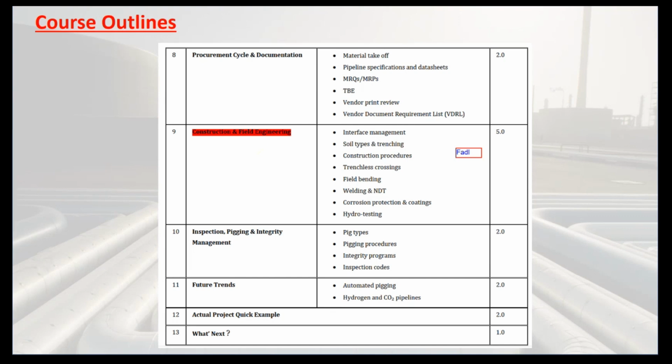Also, in some parts of the project, we will be looking at pipeline P&IDs to extract data from them. Also, pipeline P&IDs are not a deliverable of the pipeline engineer. It's a deliverable of the process and flow assurance engineers. But we need to take a look at them, and you need to know every line that is connected to a trap or a pig or any component of the pipeline on the P&ID. You need to identify it, and you need to read it carefully and understand it.